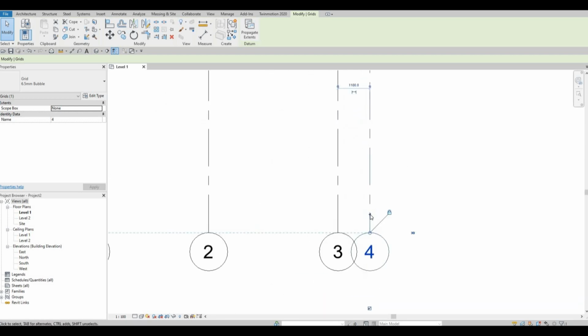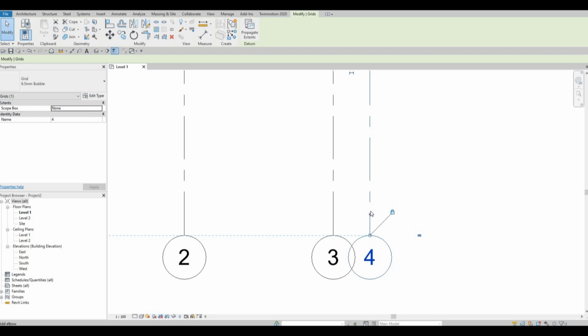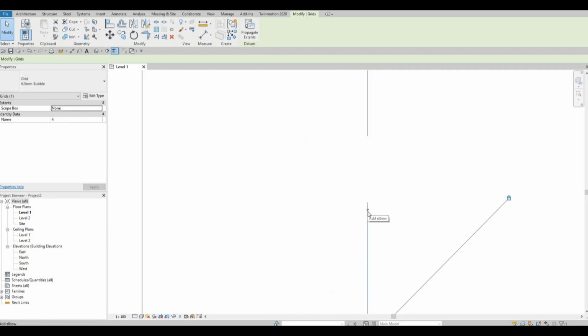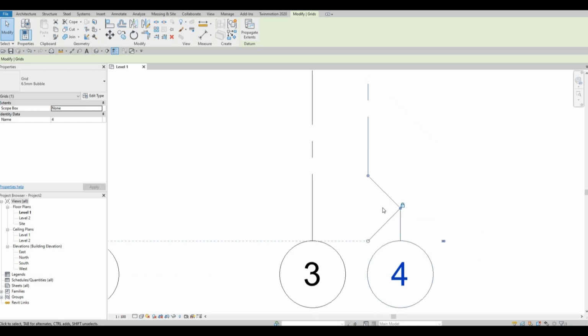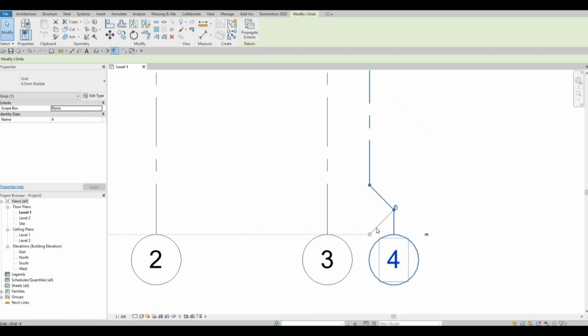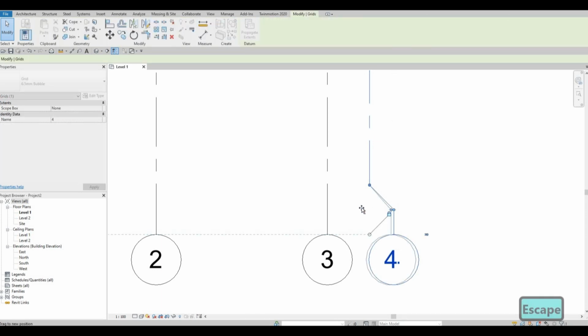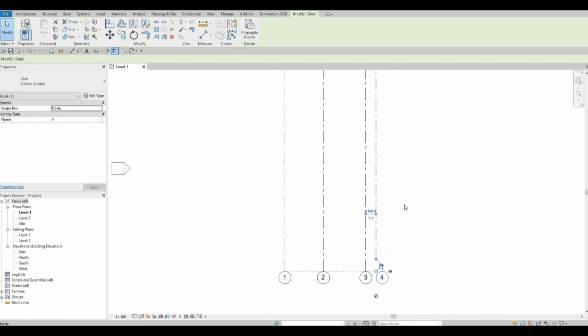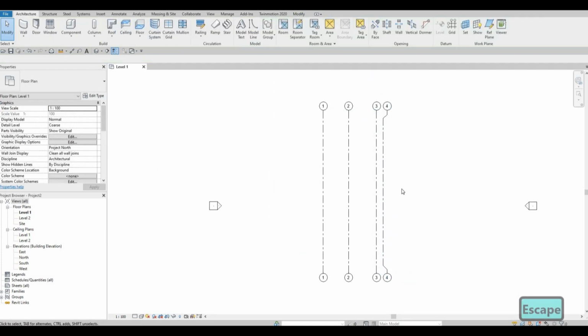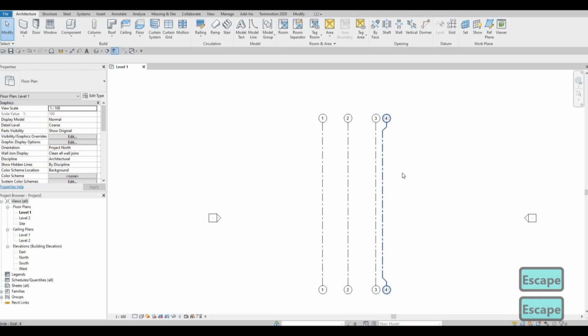Here as well, let's click on this icon. It's a small zigzag that adds an elbow. It recognizes that we want it on the right side, and if you don't want it, you just need to click it again and then drag it, depending on what you want. Now press escape and then escape again.